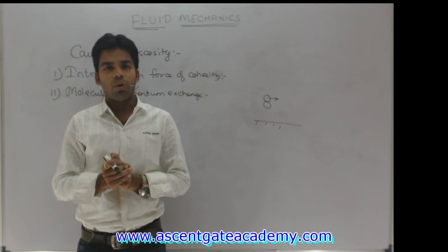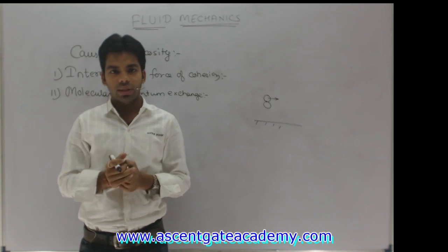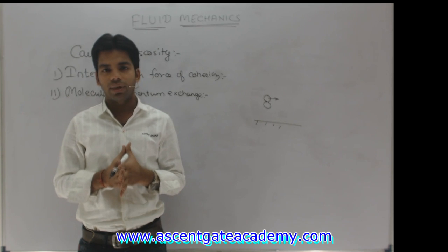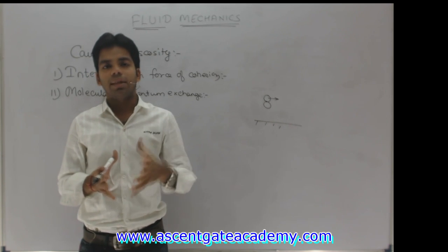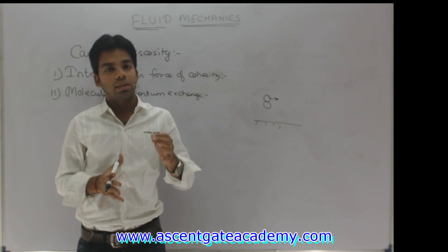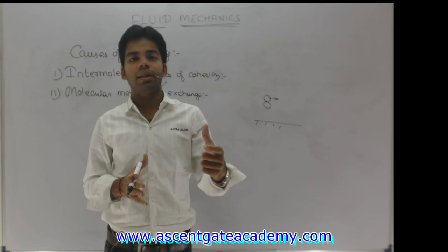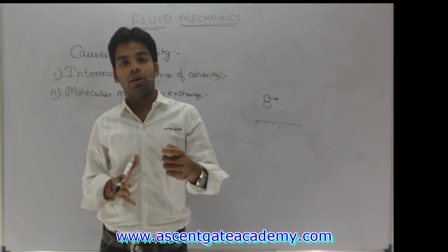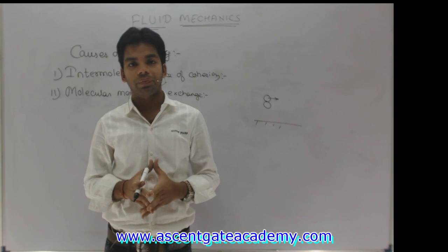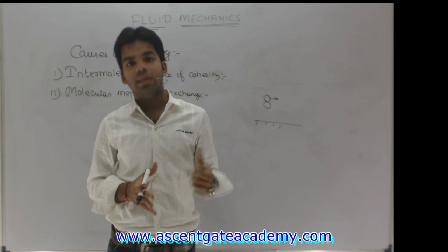Now coming to a very important point, if we are increasing the temperature of a liquid, what will happen to the viscosity? And if we are increasing the temperature of the gas, what will happen to the viscosity? Let us understand this thing very carefully. If we increase the temperature of a liquid, what will happen? The force of cohesion decreases. And if the cohesive force is decreasing, that means its viscosity will also decrease. Getting this or not? So for liquid, if I am increasing the temperature, the viscosity decreases.